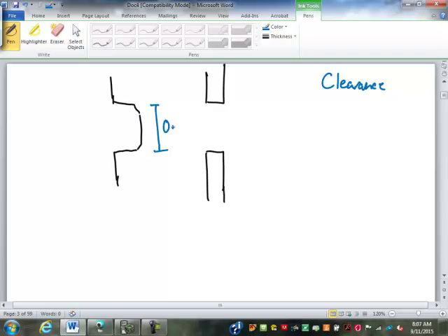So let's say that this is a 1/4 inch locating pin. And since it's not a vital piece, we're going to give it a relatively rough tolerance of 5 thousandths. Then over here we have the hole that it's supposed to fit into. And again, since it's not an acting connection, a fairly rough tolerance.